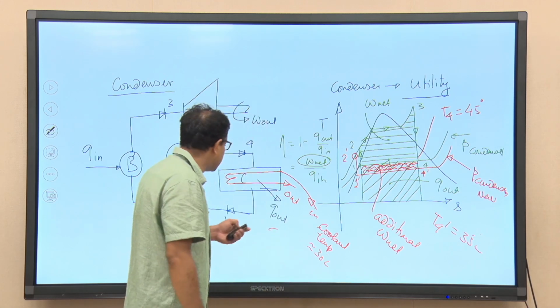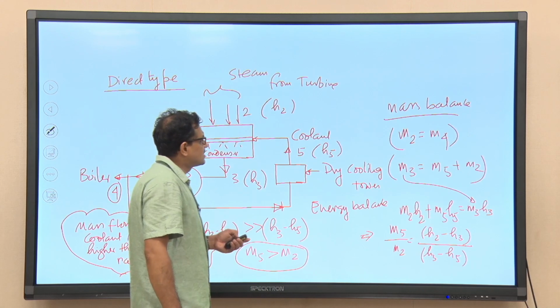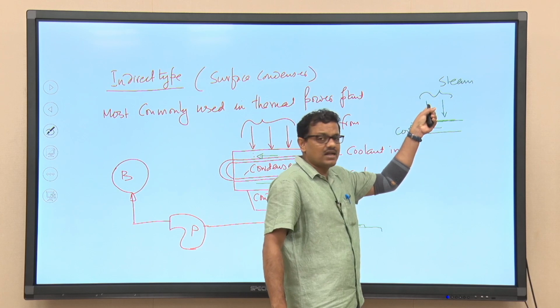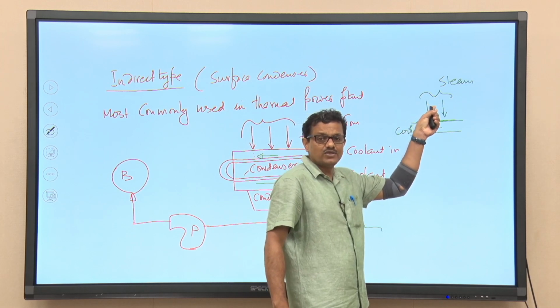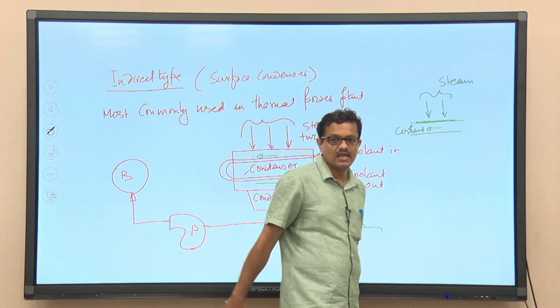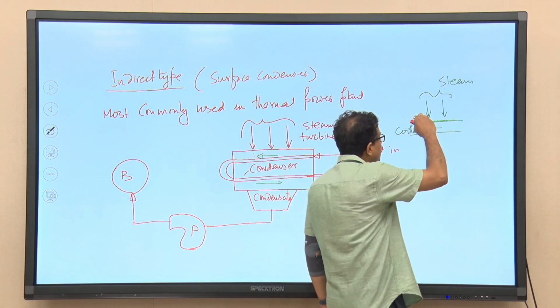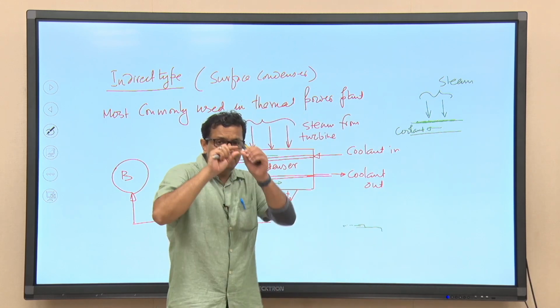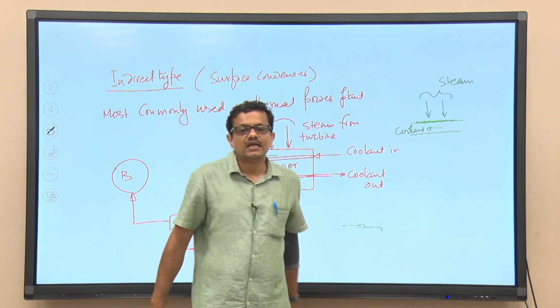So, when air is getting into the condenser, this problem will be there. So, when steam will condense in the form of a drop and the air which is there due to the leakage, that air will create a thin film, and that thin film air will lay on the tube surface, and this thin film of the air will reduce the heat transfer rate.